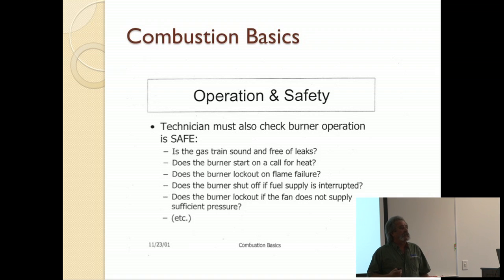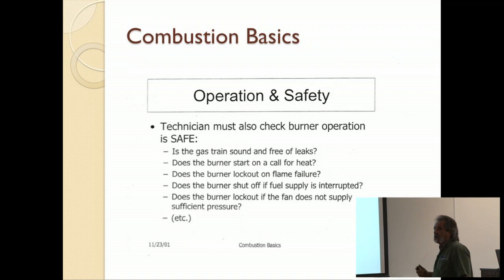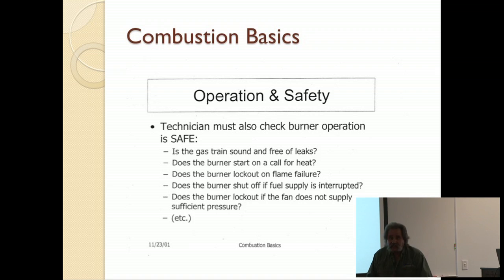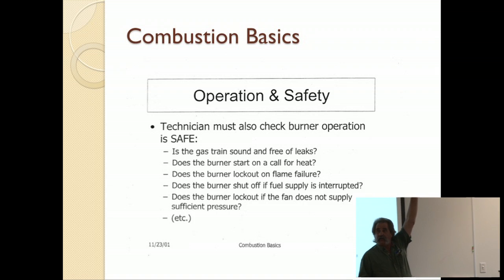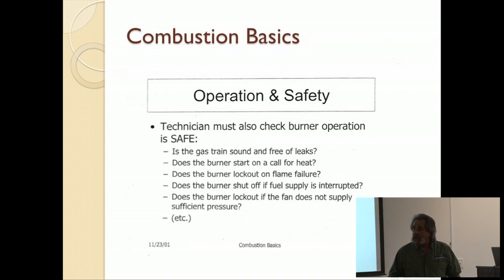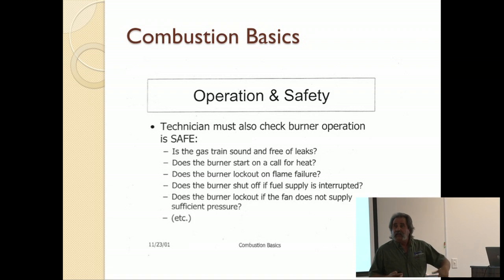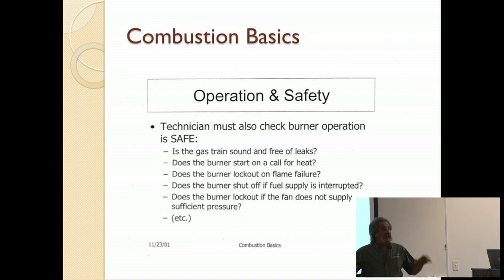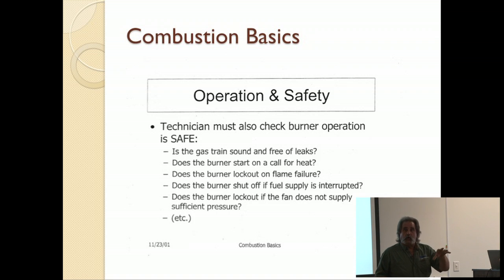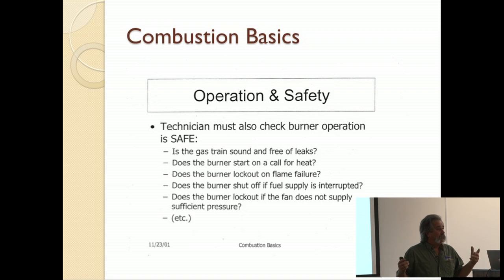And I had been in this room several times. I went ahead and lit this boiler off, and it puffed, and it lit, and I bent down to look inside the window. Bear in mind, on a 750 horsepower boiler, the control panel is right about here. It's just about all you can do to reach the bottom of it, so you have to have a ladder to get up to it. I'd moved it out of the way. This thing lit off beautifully, on liquid propane, but there wasn't enough room for it to all expand. So it blew the doors open.